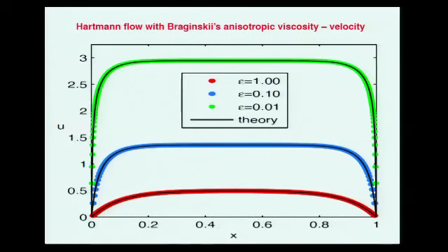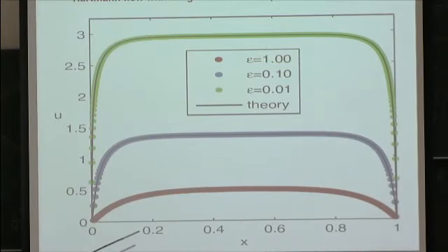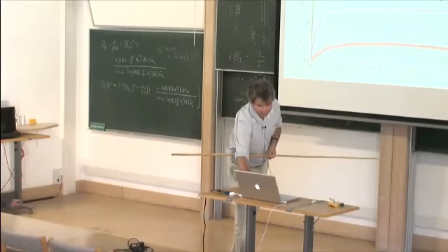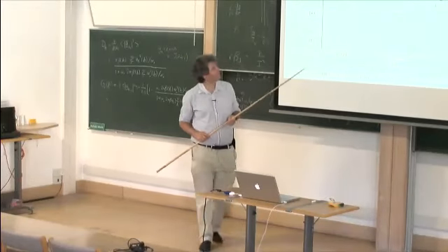And similarly with the velocity, the highly accurate and trustworthy solutions of the steady state ODEs are these black lines. Lattice Boltzmann are the thicker coloured lines, and it agrees very nicely. And it converges, at least so far.